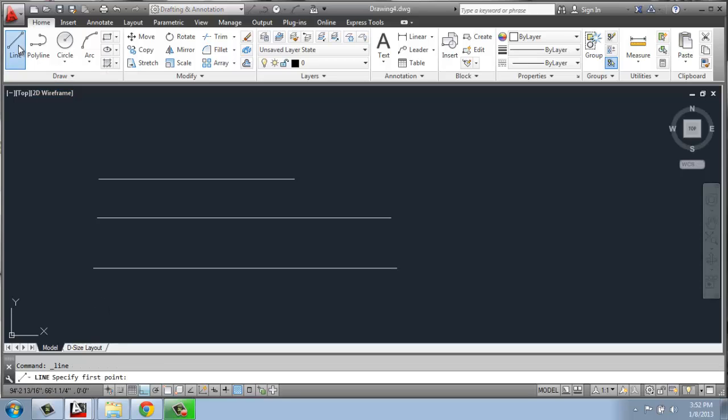When I'm actually creating lines, I can say 15 feet 6, and I actually don't have to put the inch mark because it's defaulting to inches. So I can simply do 15 feet 6, enter, and it's the same thing as the one I just previously did.